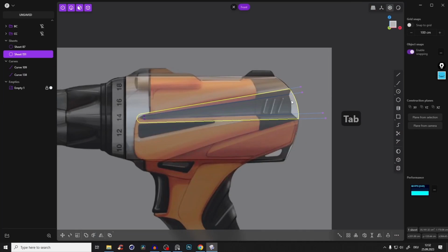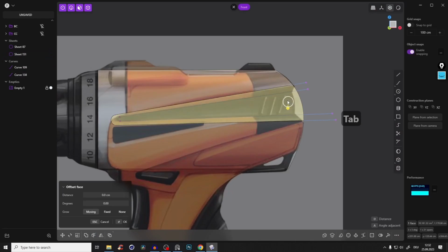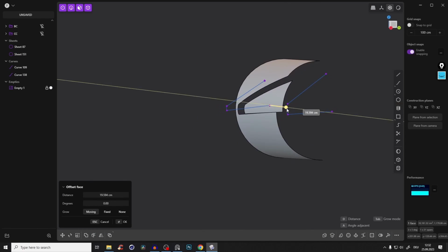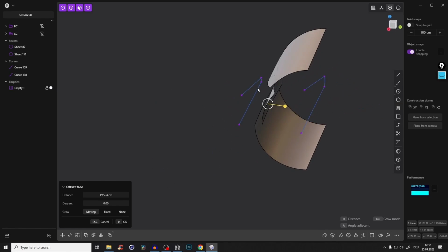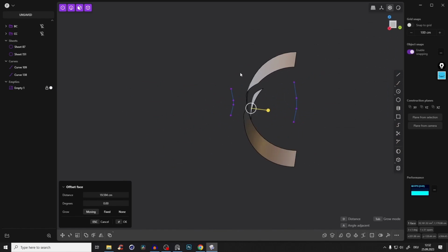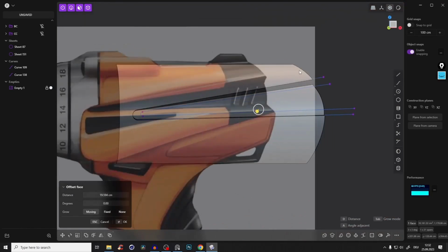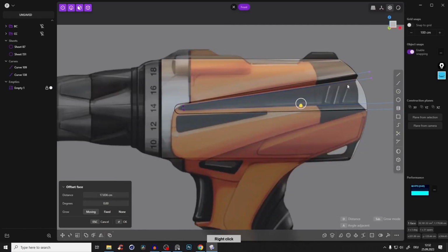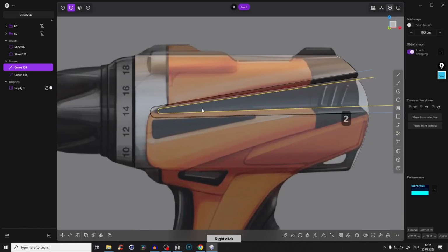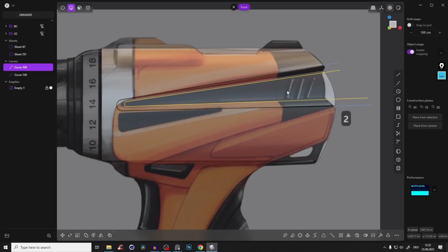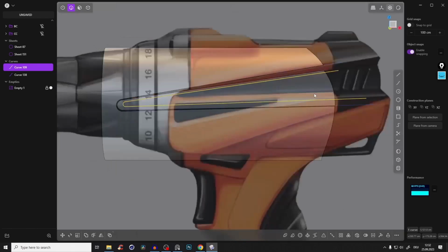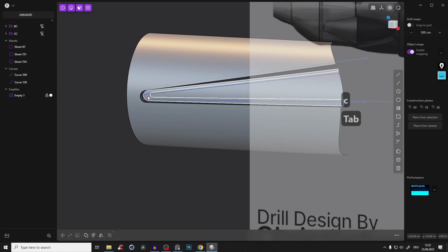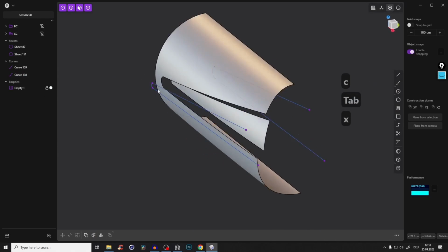And now we can put this surface again a little bit. So if we select it, we can offset that a little bit inwards, right? So here again, we have to guess. We don't know how deep it is, but I will guess, something like that should be fine. Maybe like that. And now we have already here this curve to further improve and optimize our shape. So we cut with this curve, this sheet, press OK. And we don't need this sheet anymore. And you see we get something like that.